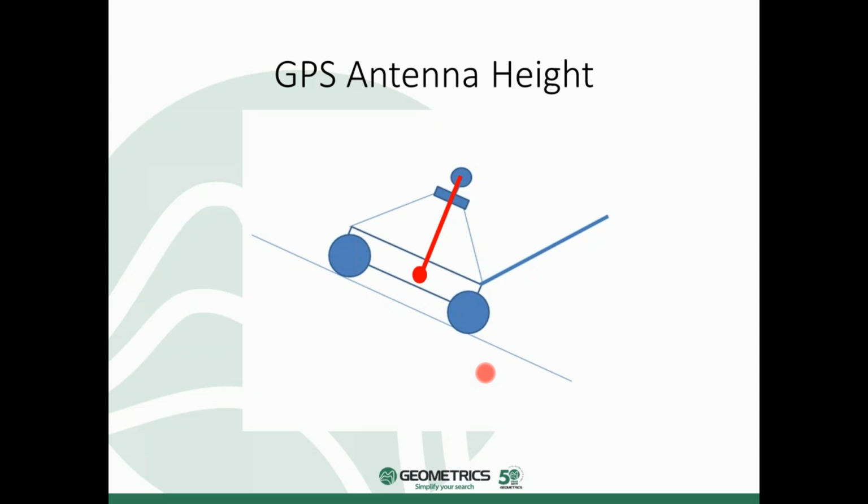But it will also report an attitude corrected UTM position. And so the UTMs are calculated using a lookup chart, and the UTM position that's reported is the 000 reference point that's referenced in all of the sensor geometry metadata within the file. So that's shown here by this kind of red circle. So that's the position that's reported as the UTM position. And that's also the position that's displayed in the navigation screen.